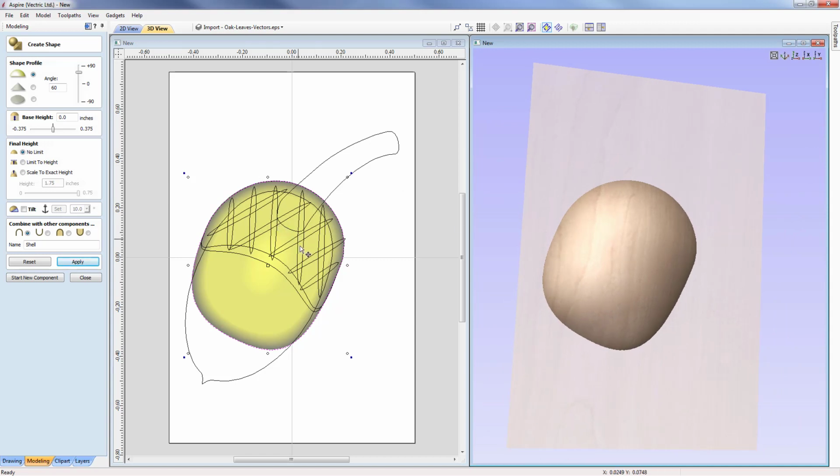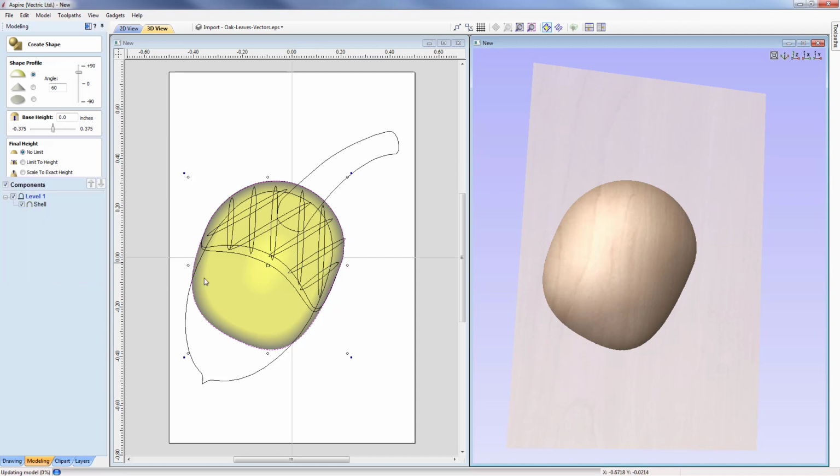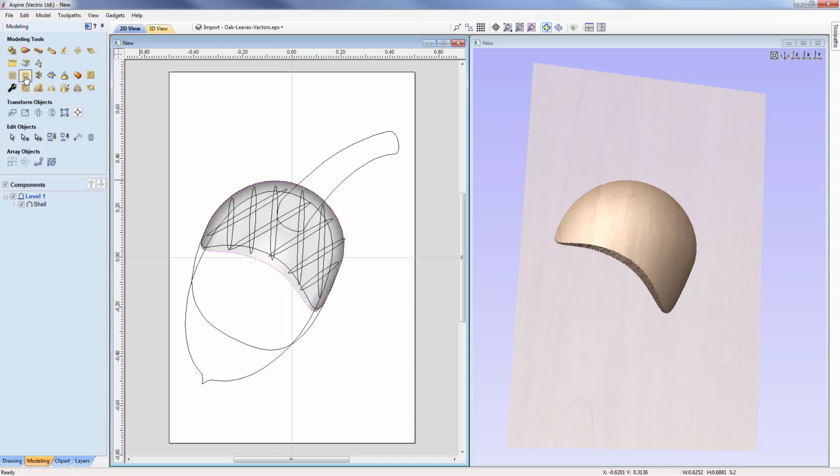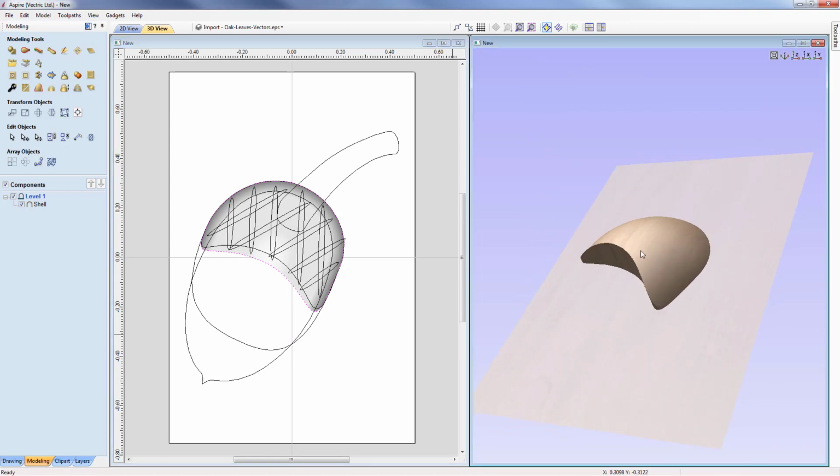Now what we're going to do is to limit this bulbous shape back to create the vertical face of the shell. So I'm going to close out that form now, select the 3D model, and then select the vector I want to trim to. Okay, and then come over and use the same tool we used before, where it's going to clear all the data outside of the vector. So we've trimmed that away now, which gives us this nice vertical face.